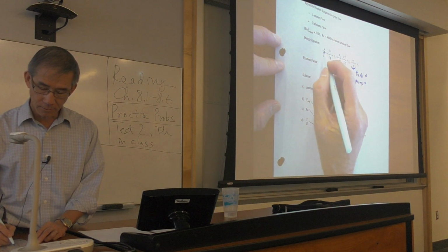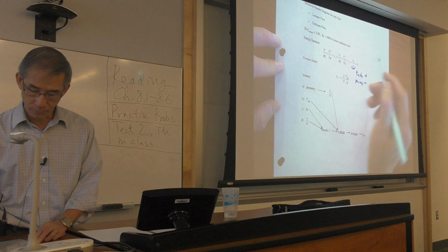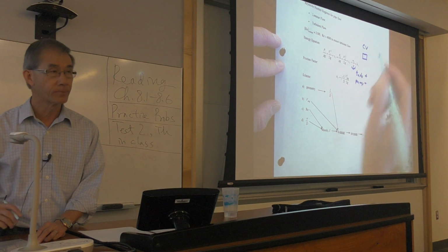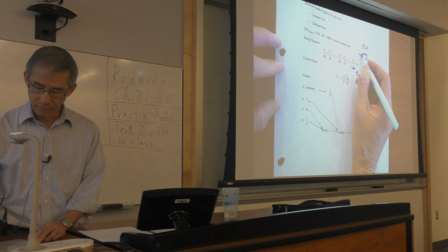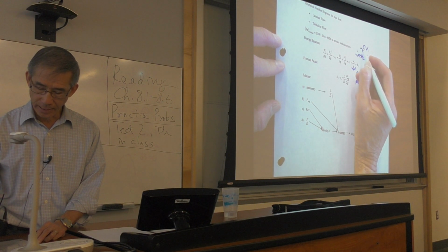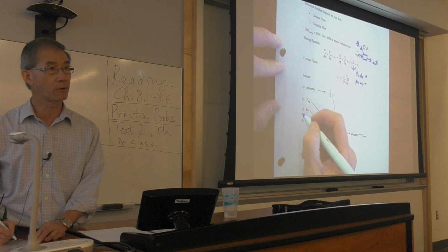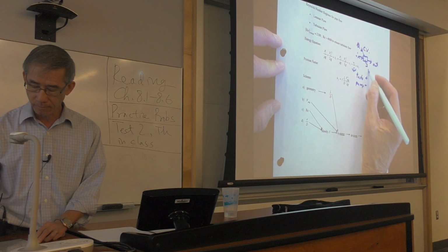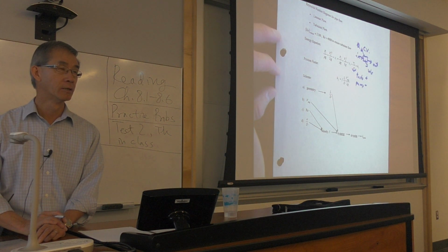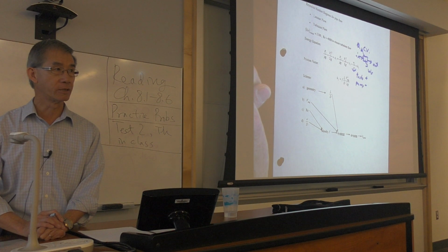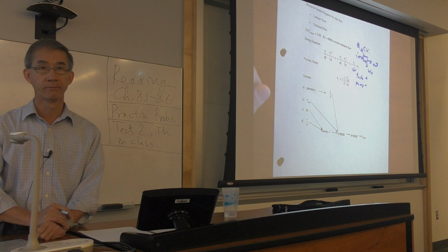Okay. Essentially, the answer is to go back to where this equation comes from, which is your first law for a control volume, not a system, right? We have flow in, flow out. You have heat added, positive into my control volume, which we assume is 0. Then you have shaft work, where our convention is that shaft work done by the control volume is positive. That's the contract we signed in the first law of thermodynamics.